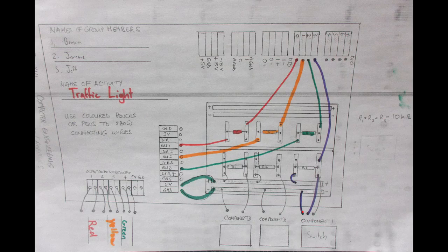To wire the switch, connect pin 3 of the switch to either of the ground connections on the pin header, and pin 1 to a row on the breadboard. In the same row, insert a resistor into one of the nodes. A wire will connect the junction of the 10K resistor and the switch to the digital output line 3 pin header. The resistor is also connected to either of the 5-volt outputs. Now the switch has also been properly wired.